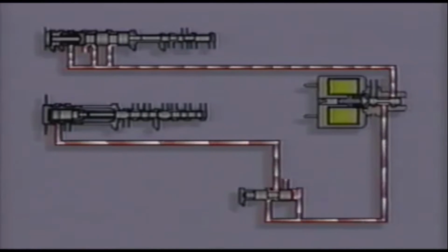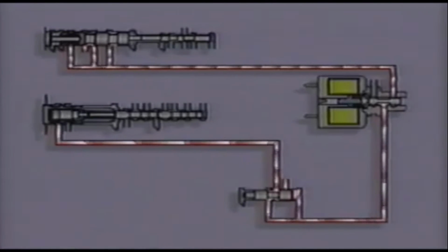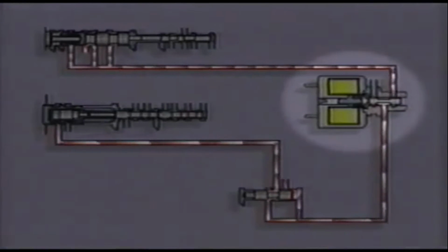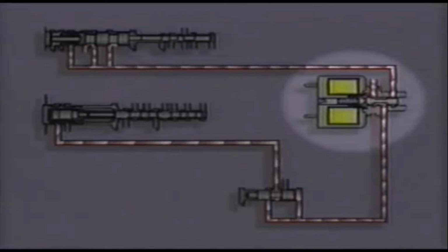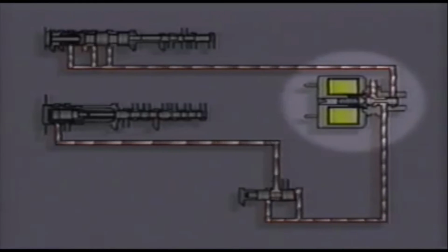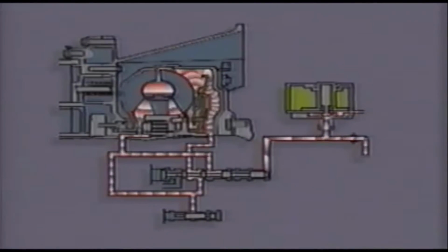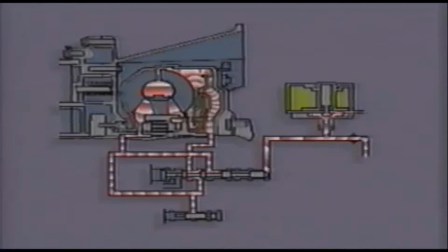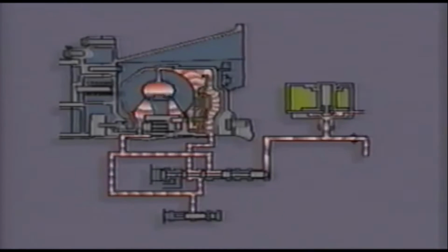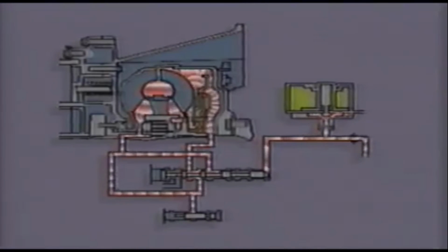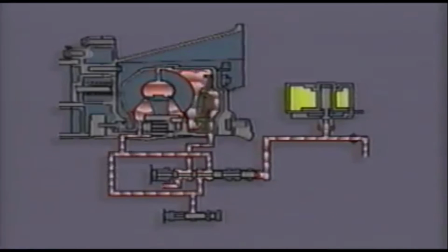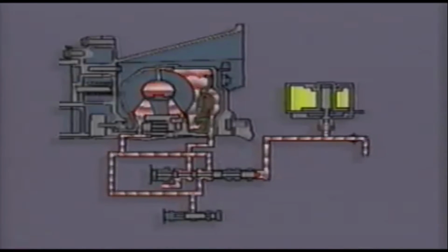Variable force solenoids control the amount of core movement depending on the varying ground provided by the processor. These are used to control transmission shift feel, for example, by varying the amount of applied pressure. Operation of the torque converter clutch in some transmissions is also controlled by a variable or modulated solenoid that allows a controlled amount of slip to occur during clutch engagement.